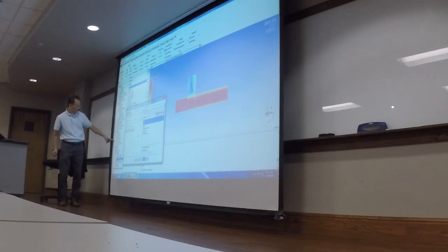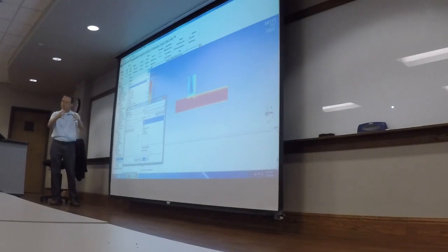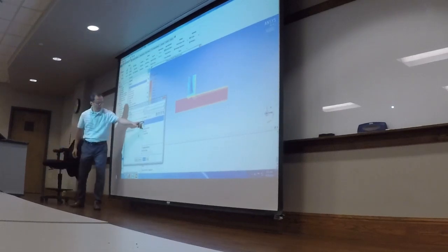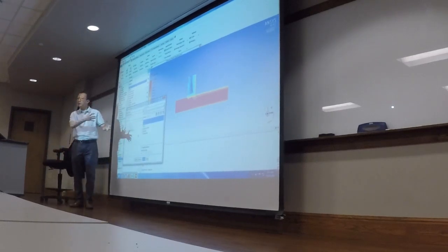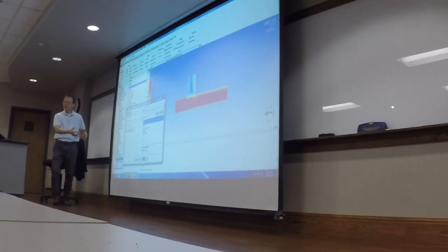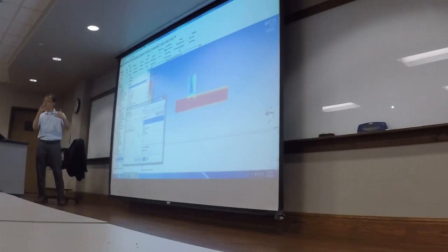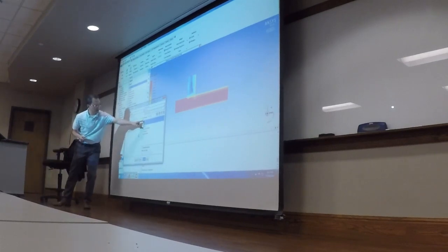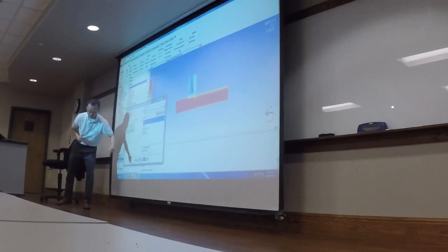I would like to see reports, surface integrals. So the integral means sum mass flow rate from what surface? From exit 1 and exit 2. I would like to see the mass flow rate distribution. Don't forget, when it comes in, it's 1.0 kg per second. Compute. So after you select exit 1, exit 2, compute.